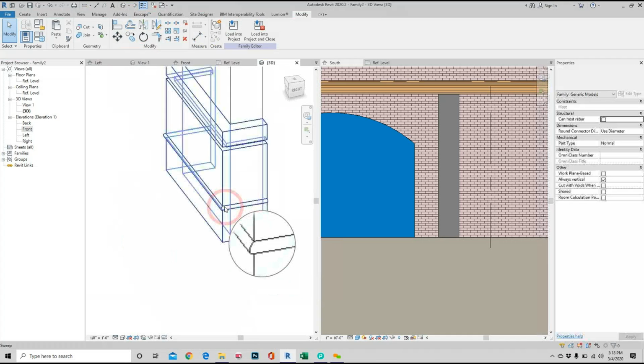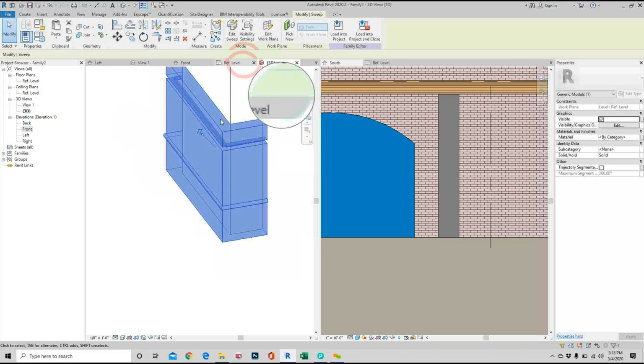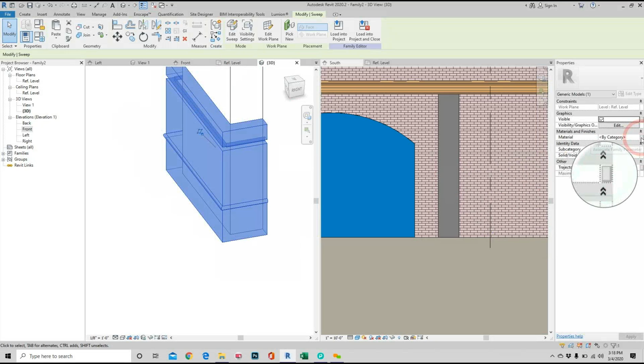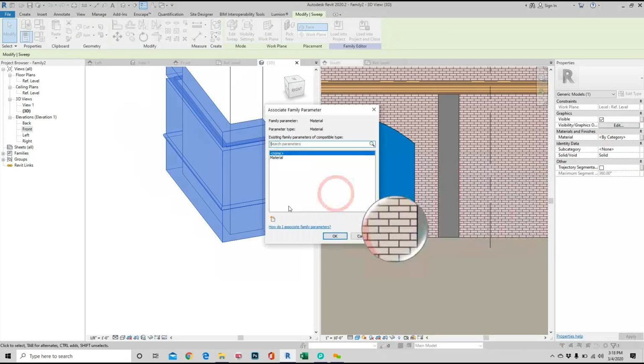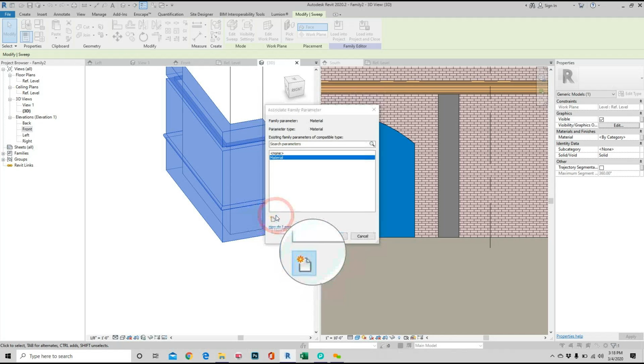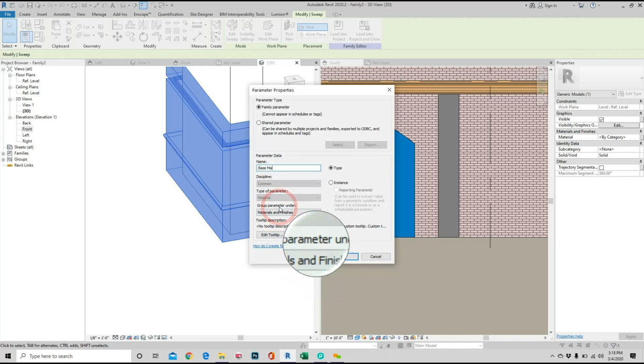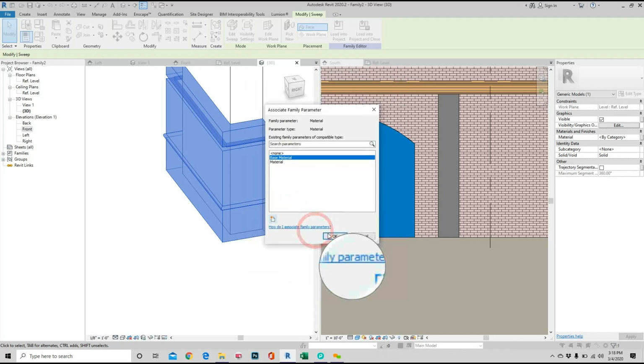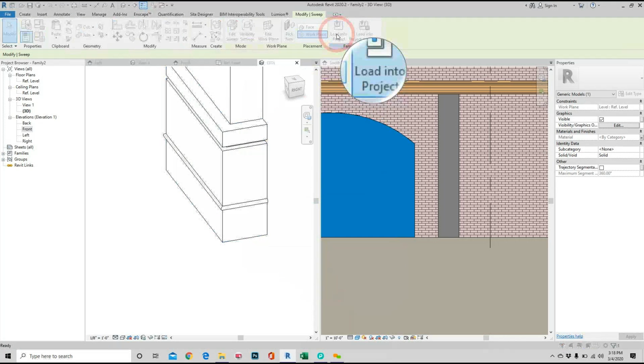All right, so once I do that, let's put material, select that piece. Again, I can go to my properties here. I find the assigned material, and if I wanted to use the same column material that I did for my pilaster, let's say it's going to be painted white because it's wood, I can just do this and use the same material. So when I paint my pilaster, this gets painted too. But let's say you're fancy and you want something different, I would just add a new material. Right? And I would say base material. Be specific.